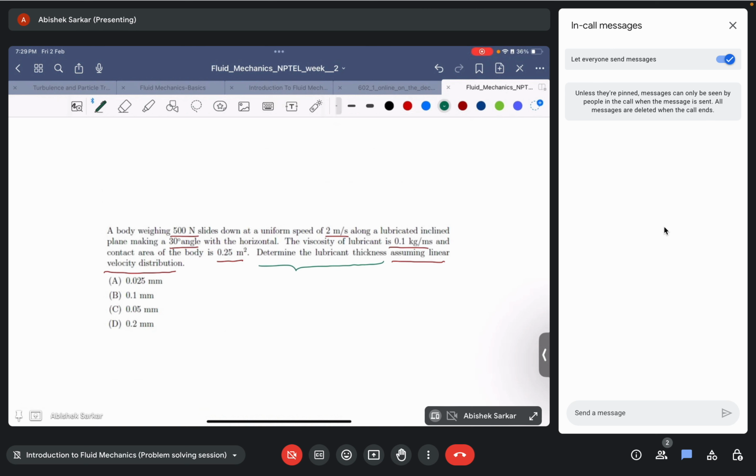I'll give you a few minutes to formulate the problem, draw the diagram, and solve the question. It's quite simple. I'll give you a hint: in the case of a linear velocity distribution, you can consider u to be V y by h, where V is your uniform velocity, in this case 2 meters per second, y is the distance from the wall of the plane to the lower surface of the body, and h is the gap between the two,